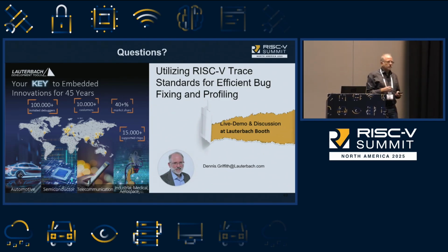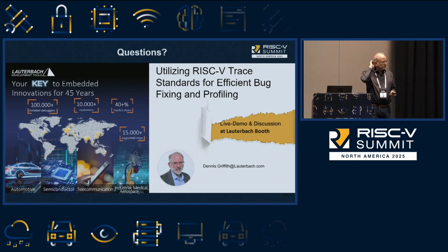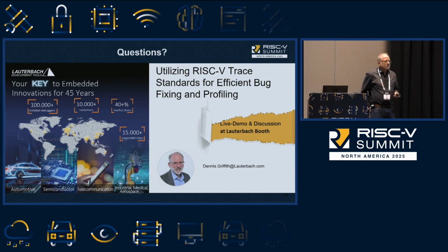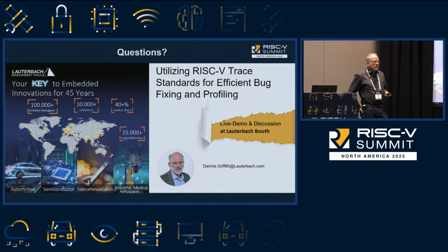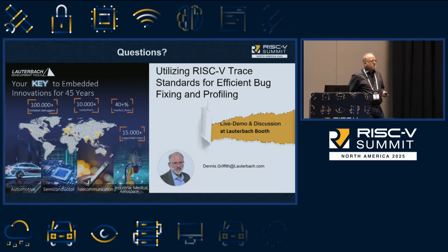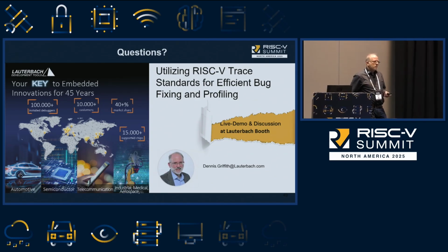When I use trace hardware, like CoreSight, the problem was the trace buffer, like the STM and ETM, is wrapped around without any facility. If I don't use any facility, and I use your trace probe, can I get the trace in real time, for a long time?